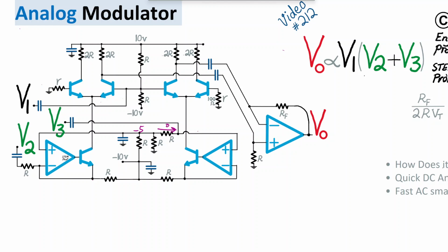As a result, that negative 5 volt appears at the positive input terminal of the op amp, and because op amps are properly biased, meaning that op amps 1, 2, 3 are properly supplied with the plus 10 volt and minus 10 volt supply in this example, the virtual short will be there with guarantee that the voltage at positive and negative terminal is the same.